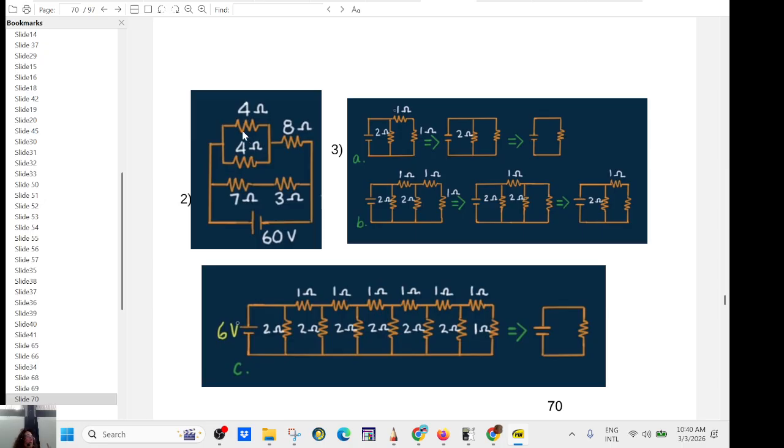Okay, so if you have two branches and the resistance is the same, you divide by 2. If you have 3 branches, divide by 3. Otherwise, you do it. So 2. So you have 2 here and 8 here. How much is that? 10. So you have 10 in parallel with 10. So the equivalent resistance will be 5. And then you do 60 divided by 5. Yes, and that will be the current that you drain. Huh? Isn't that cute? It's a nice unit. It's much easier.